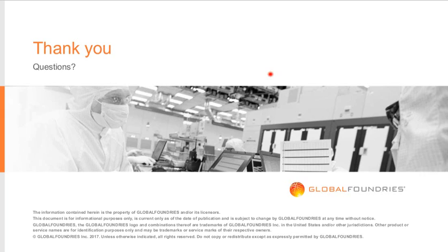So basically, we tune the model for the device level and also the circuit level to make sure the device is good enough for different applications. And for the RF FET, the thermal self-heating is also included in there. This is a very important one. So we also support this for thermal simulation for the PA.